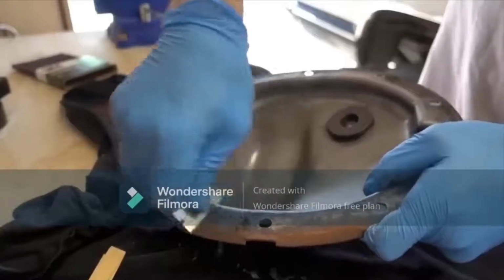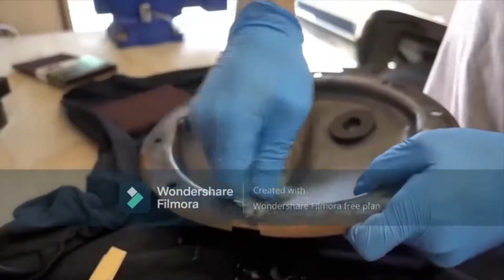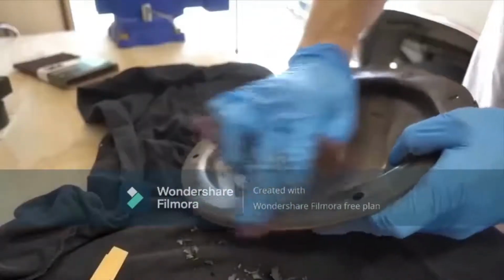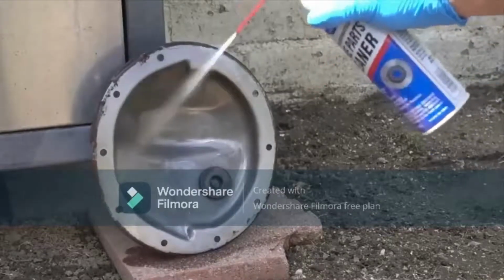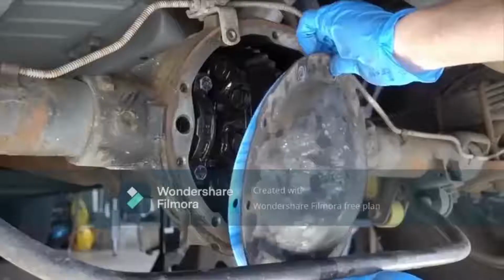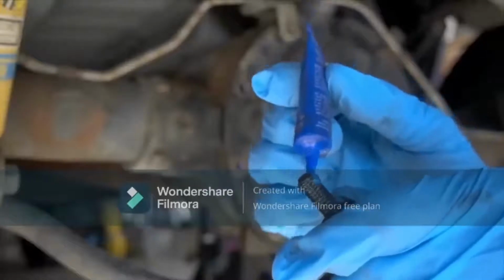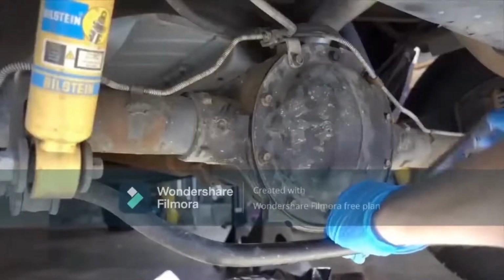Use any thin, sharp and strong blade such as a razor to scrape the remaining gasket material attached to the differential cover, and use a sanding pad or very fine sandpaper to smoothen the surface. Clean the LSD cover and the gears inside with alcohol by spraying onto it. Then place a new gasket on the differential cover. Apply grease or thread locker to the bolts, then tighten the bolts with a ratchet.